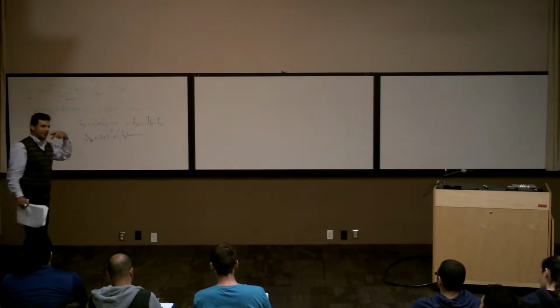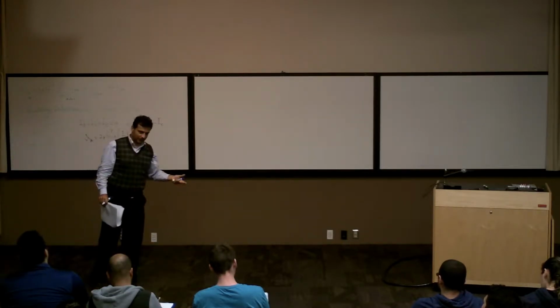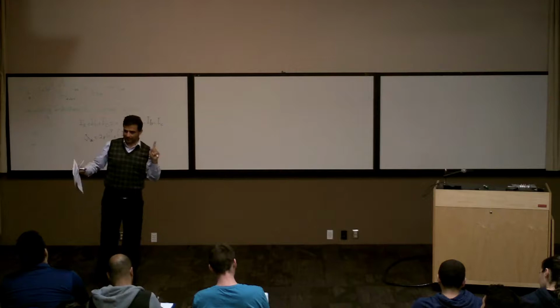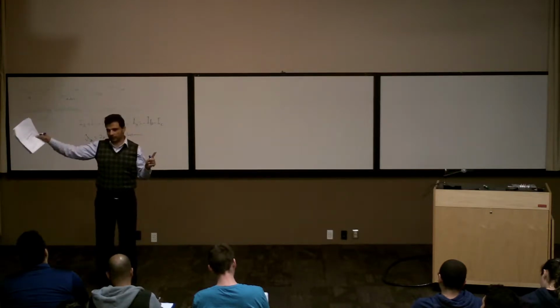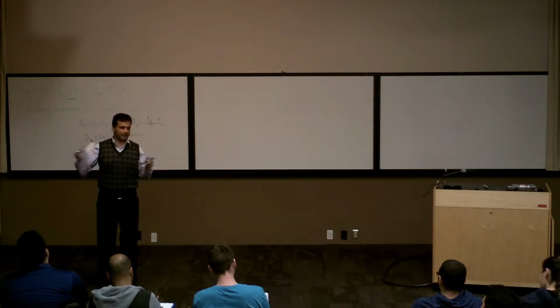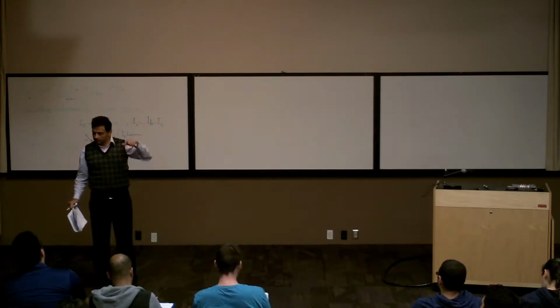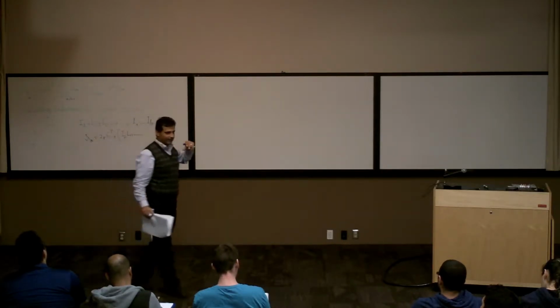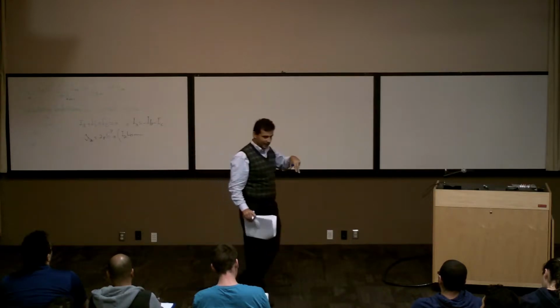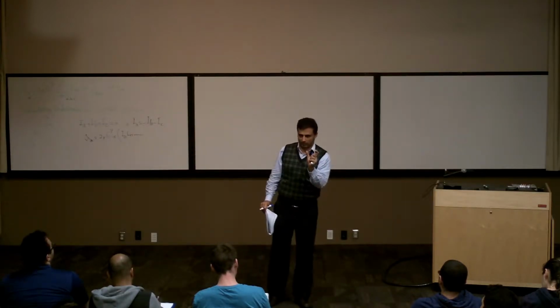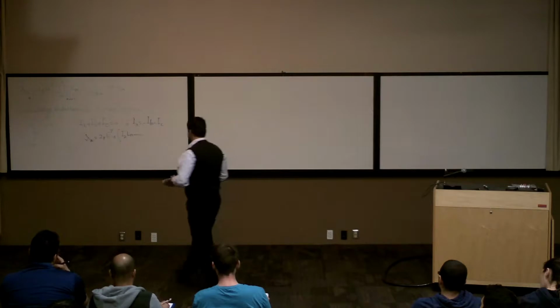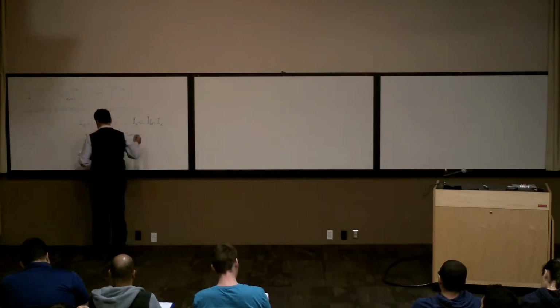Let's say the distance of a conductor to itself. Call it this way, because we have a distance between this conductor and the next conductor. For example, we call it DAB. This conductor to the other conductor, we call it DAC. But the R prime, we can define it as a distance of the conductor to itself, which is the R prime. R prime we calculated before. So basically, it's going to be 1 over R prime.